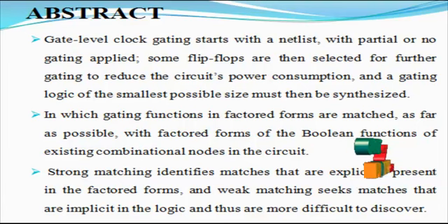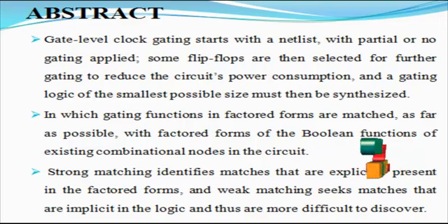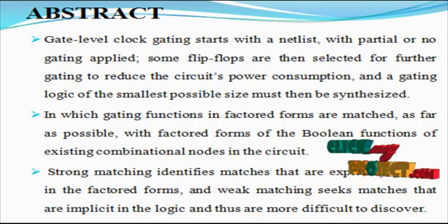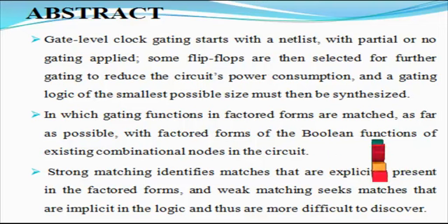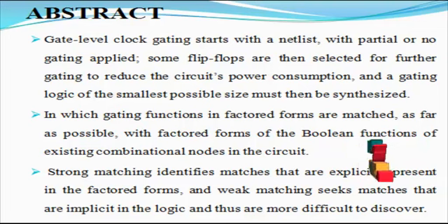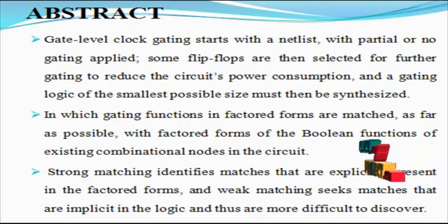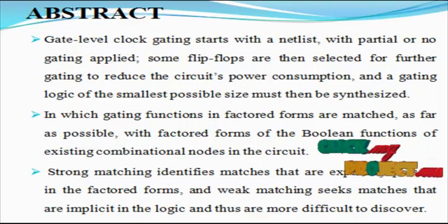The clock distribution net and registers typically use up 40% of the power consumed by the processor. Techniques proposed for reducing the clock power include blocking unnecessary clocking of registers by clock gating, using dual-edge triggered flip-flops to halve the clock frequency, and sharing clock inverters by merging several flip-flops into multi-bit flip-flops. Clock gating is the most popular among these techniques and has now become a standard design practice.